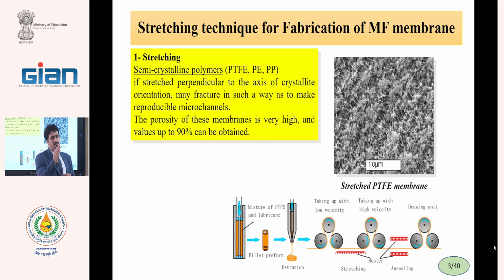And changing of this liquid phase to solid phase is named phase separation or phase inversion. Phase inverse from liquid to solid, okay? Therefore, in phase inversion or phase separation, we have a liquid phase. The liquid phase can be from melting or from dissolving in solvent, okay?